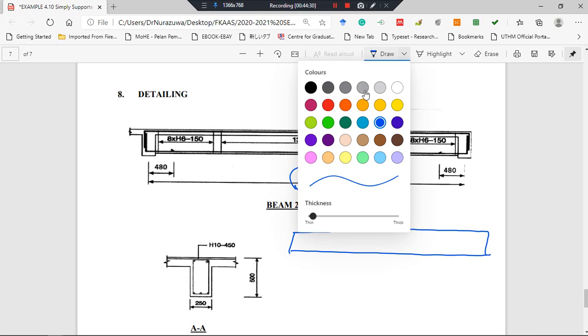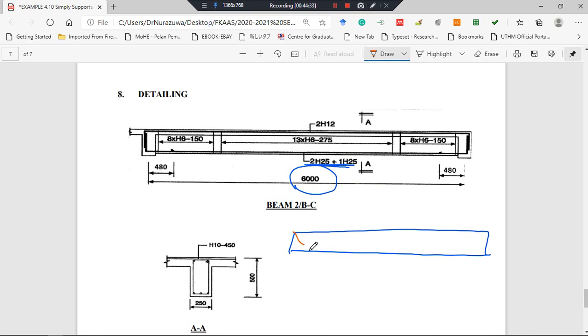We know the maximum moment. Okay, this is the maximum moment. The maximum moment occurs here, at midspan. But when it goes to the support side, it starts to decrease. From 0, it increases here to the maximum, then decreases back. So this here is 0. For the same purpose as the minimum shear link, to reduce the cost, we reduce the steel area at the low moment.